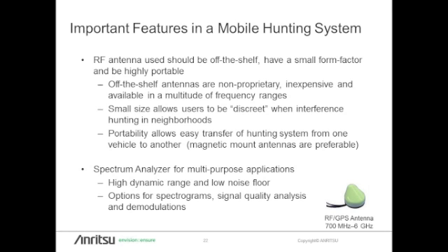You want a multi-purpose spectrum analyzer, something with high dynamic range, so you can see the low signals in the presence of the large signals. You want something with a lot of options. You don't want something just for the interference hunt while you're mobile. You want something that you can identify the interference with. You can do quality analysis. You can look at the kind of signal it is. You can look at the history of the signal and many other things to get you a major head start in your interference hunt, which is pretty crucial.